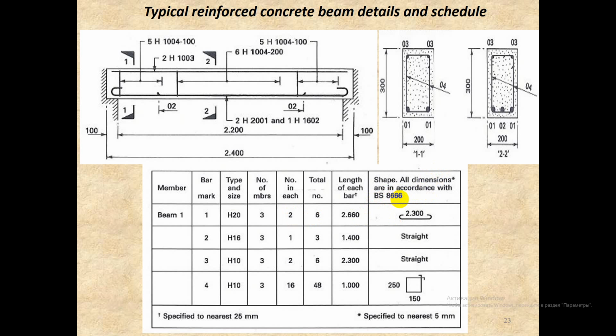These give details of the common bending shapes, the method of setting out the bending dimensions, the method of calculating the total length of the bar required, and a shape code for use with data processing routines. A preferred form of bar schedule is also given, which has been designed to give easy cross-reference to the detail drawing. A typical reinforced concrete beam detail and schedule is shown here.